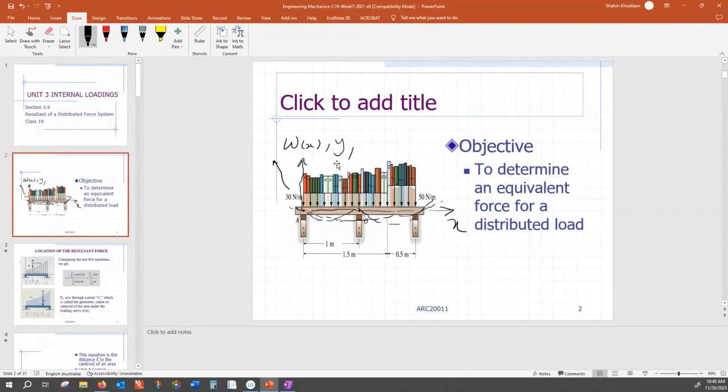And well, we are not familiar with that type of loading, are we? I mean, if I put some point load here and ask you to find the reactions, perhaps you make a diagram and do it. But if the forces are distributed, how can you solve? How can you find the reactions? So listen carefully. This is a very simplifying step. We're going to learn that today. That simplifying step is that a distributed load is equivalent to one single resultant.